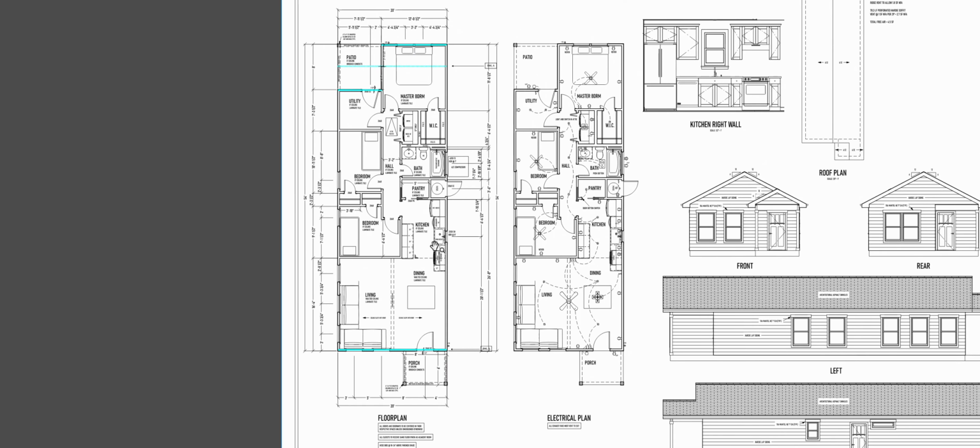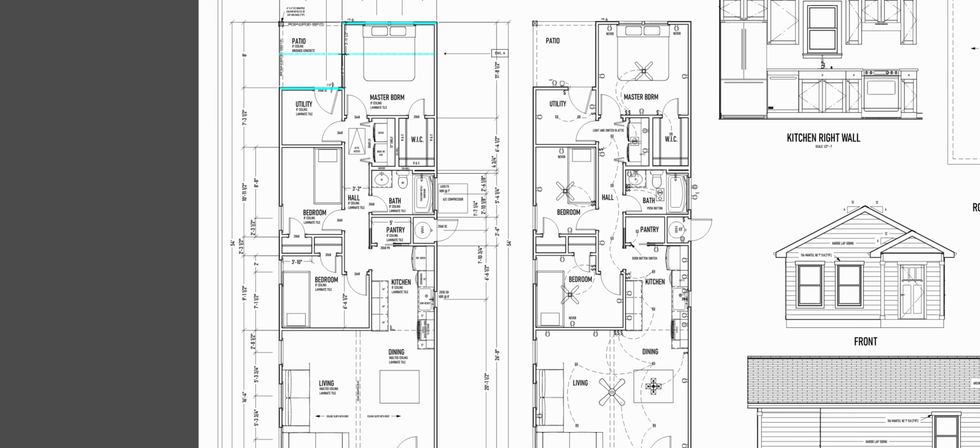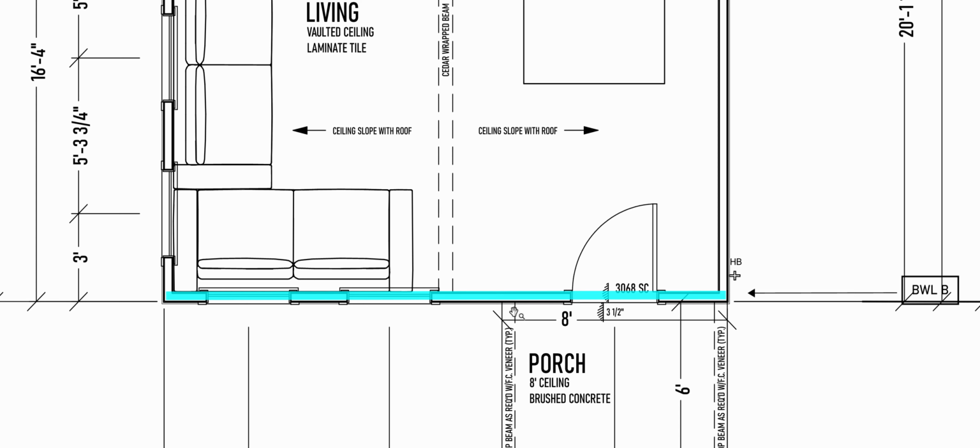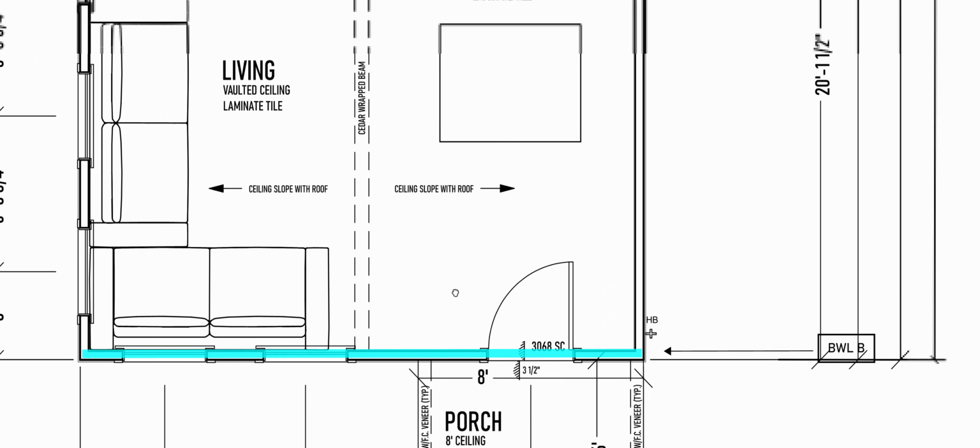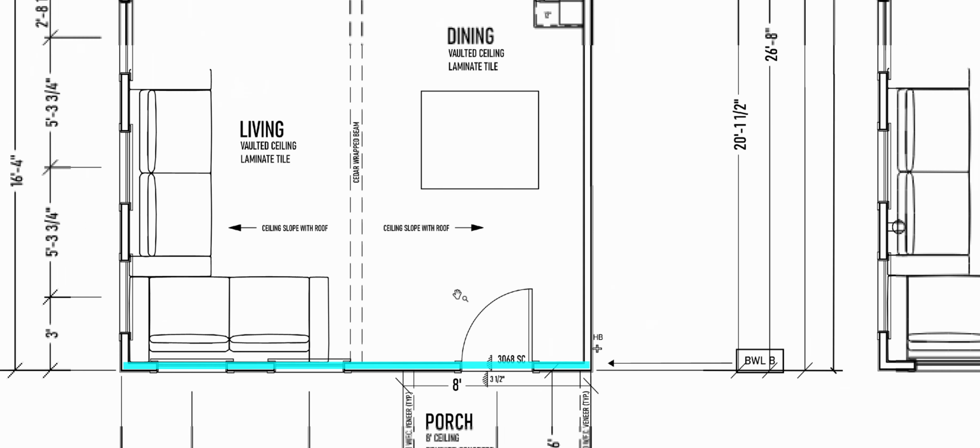However, I'm going to look at that spacing because that's a long ways to go without any bracing, and it's going to make my requirement kind of heavy for how much I need to be installing in terms of bracing. That's 50 feet. That's a long ways to go. So what that means is the farther apart these are, the more panels and stuff I'm going to need to put in this wall. And I already don't have hardly any space. I'm already going to probably have to do some funky stuff in here. So that's going to be that. But we want to possibly try something different here.